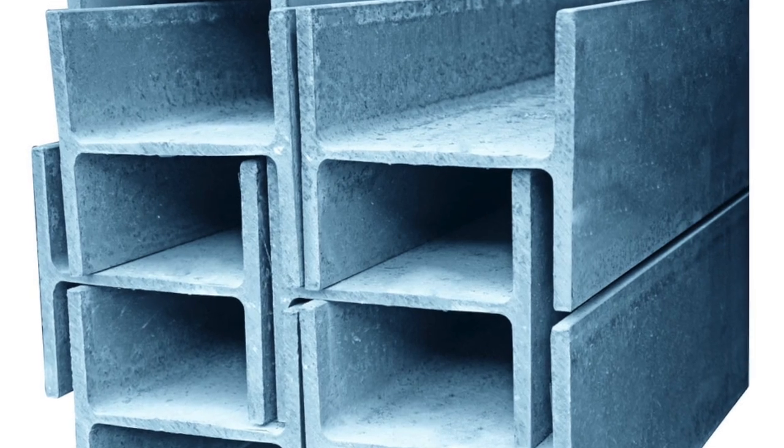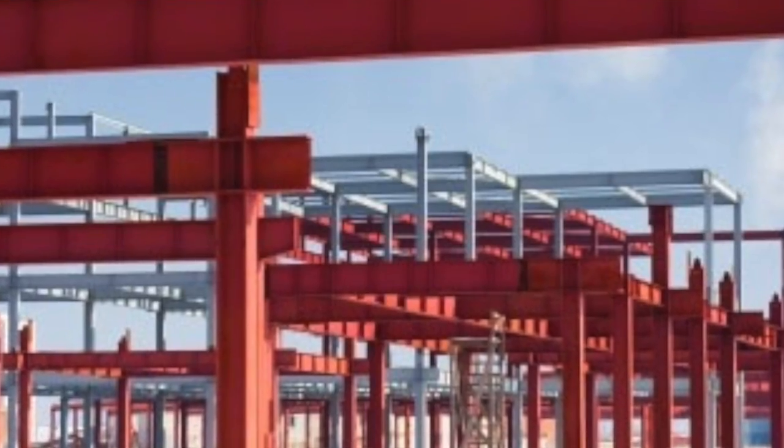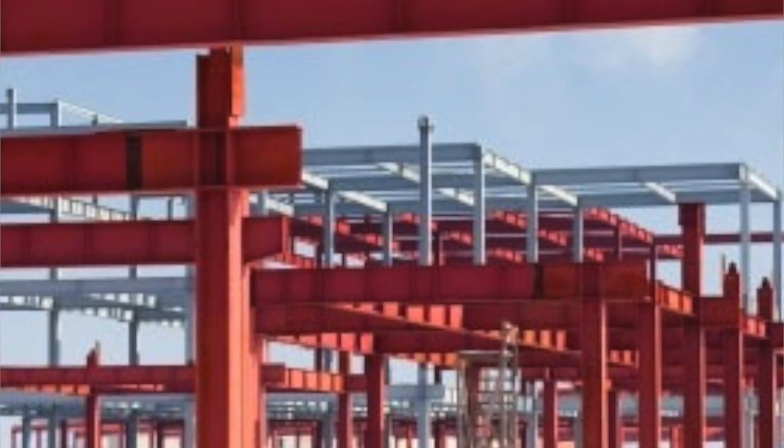Hi, my name's Justin and I'll be talking about designing a typical column. Columns are a vertical member of a structure that is subjected to vertical compressive loads. They are used in a structure for supporting and transmitting the horizontal loads from the ceiling, roof slabs and beams to the concrete footing supporting the structure. In order to design a column, 8 steps must be followed to ensure a column member selected is both safe and able to withstand the loads associated with the structure.